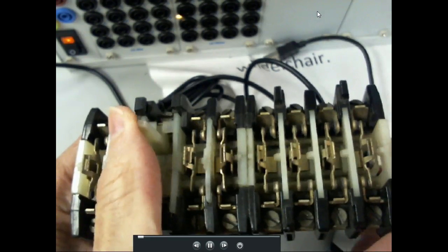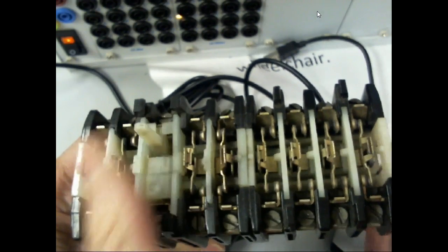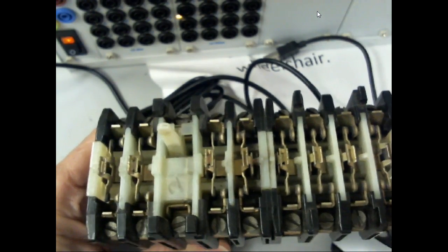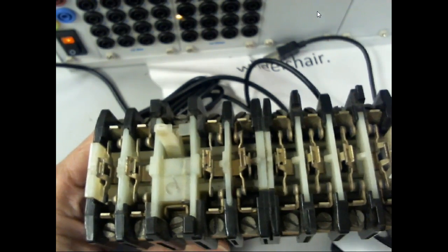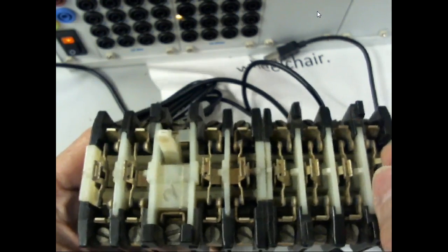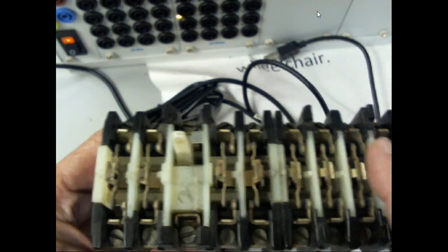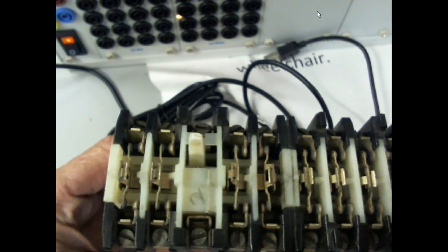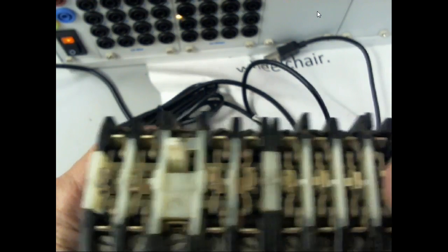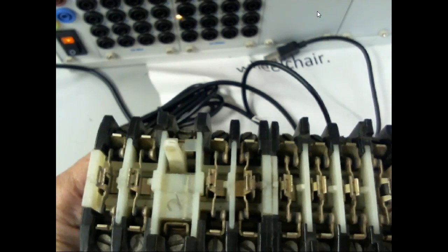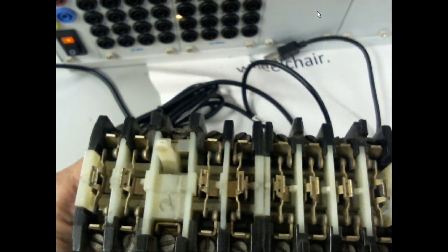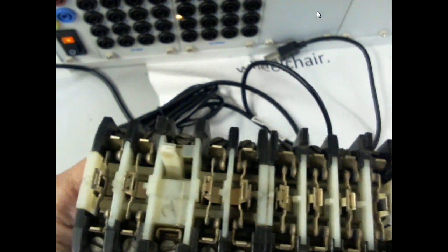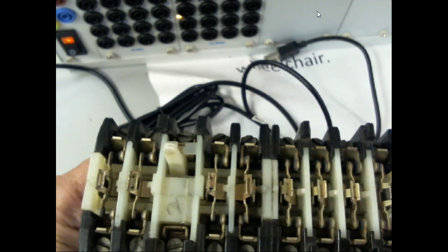This is our force, by the way. So this would be a normally closed contact, and you have to specify, or you have to rearrange these. You can take these off and you can make it normally open and normally closed, but that's mechanical. So if you need to change a contact on a relay, what would you have to do? You'd have to go out there and do it on the relay. How many of y'all have used the wrong contacts in your PLC program?